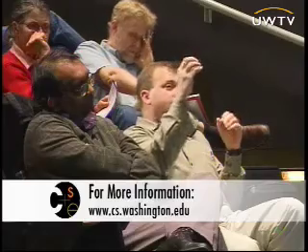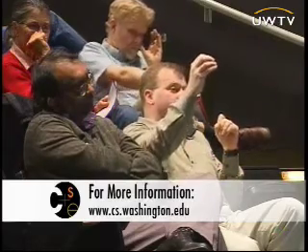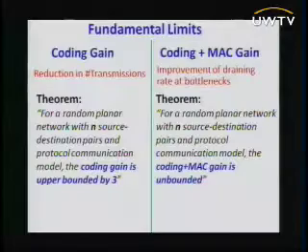Sure. So let's say for a given amount of power on these front ends for your system, I just did a brute force method. The power that I need to get this linearity, this phase noise, etc., for your system, instead of using it for your system, I just say, okay, we'll use the old, inefficient network, and I'll just increase the modulation. Right? So the question is really, what are the energy gains you get versus the amount of power I'm spending? What's the trade-off here? And this slide is the answer.